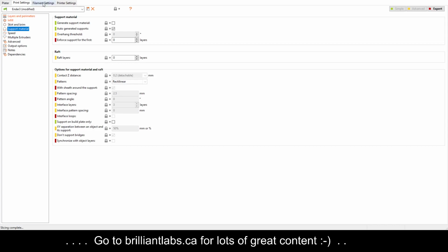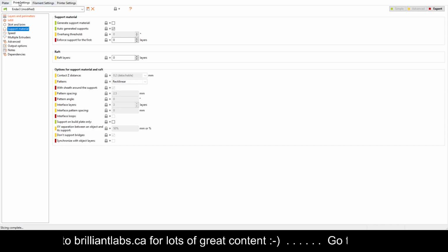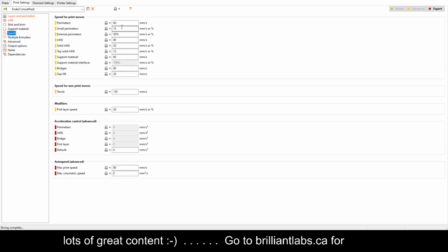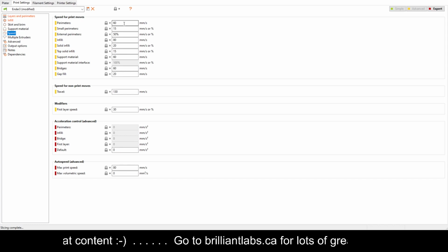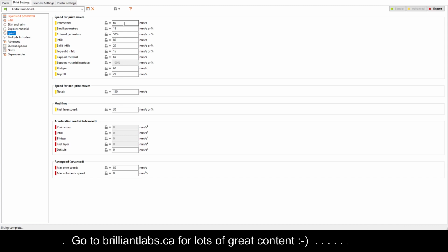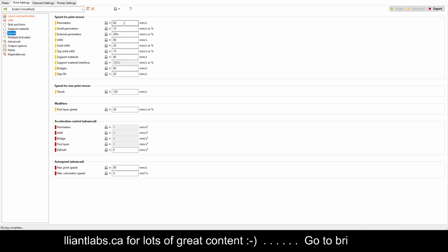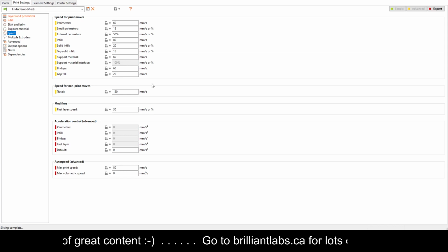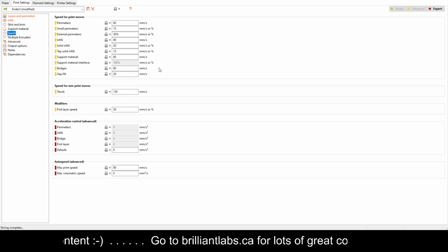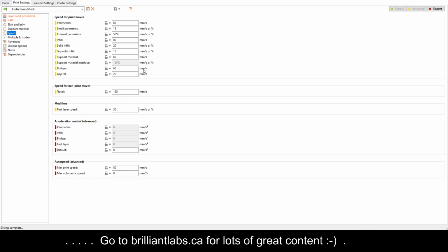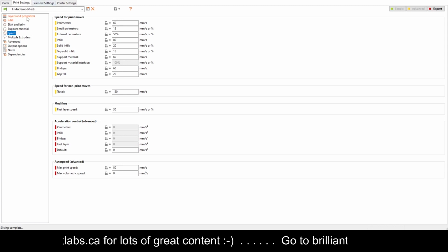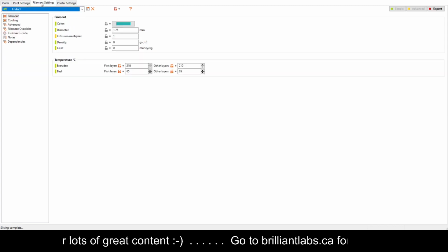All right, let's go to filament settings. So we've got our print settings basically done, the ones we need. Well, we'll look at one more, speed. Depending on your printer, 50 or 60 millimeters a second is usually enough. I wouldn't go beyond that with most printers like the Ender 3, for example. Some other printers, Ultimaker printers and so on, could probably print at a little higher speed, but I would normally leave it there. So we're going to go ahead to the next tab, which is filament settings.